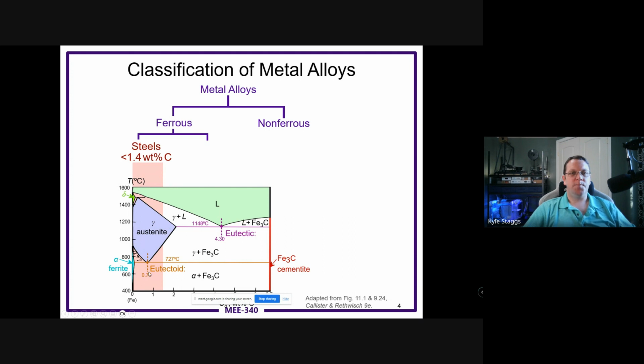And this is why the austenite regions and things are so important, so that we understand what material behaviors we can expect. When you get above those significantly, you get into higher carbon steels up here. Cast irons start above 3 weight percent. So this center region in white is more what you can think of as your tool steel region, and cast irons are even harder up in this range with the 3 to 4.5% weight carbon.